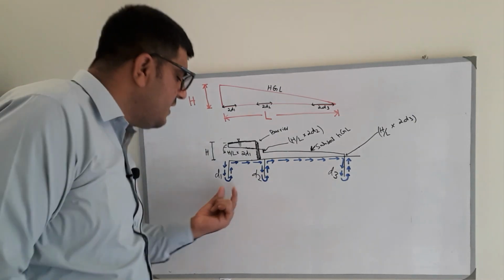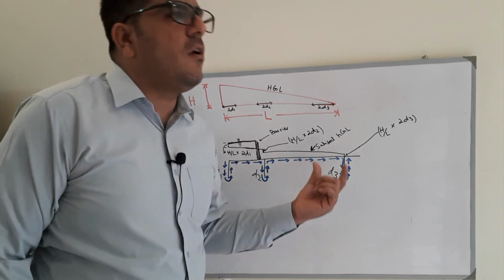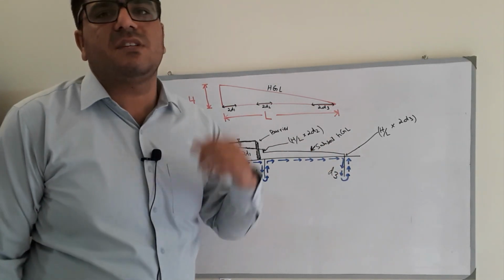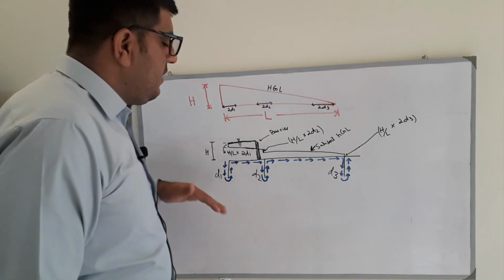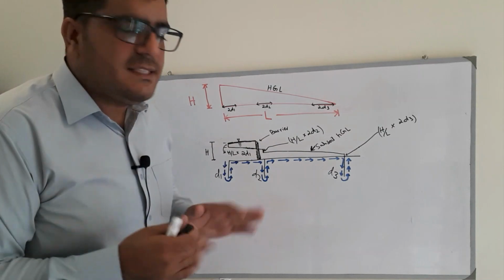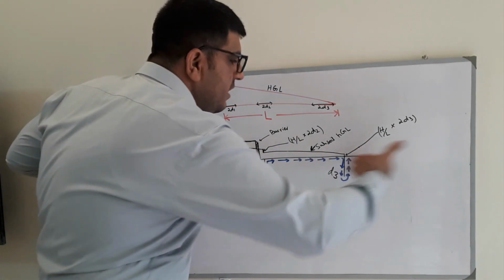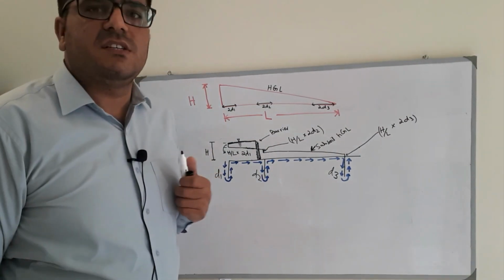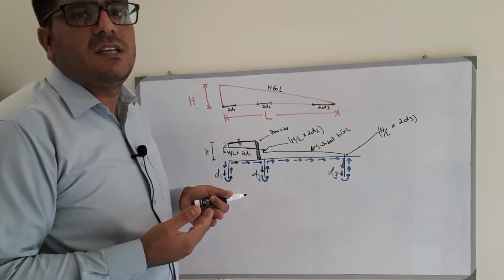So that's the reason that we provide the sheet piles at upstream, intermediate and downstream sides of the hydraulic structures, so that we can reduce the cost and it will also increase the creep length. It's not necessary that you provide the sheet piles. You can provide a horizontally sufficiently long impervious floor, but then it will increase the cost explicitly.